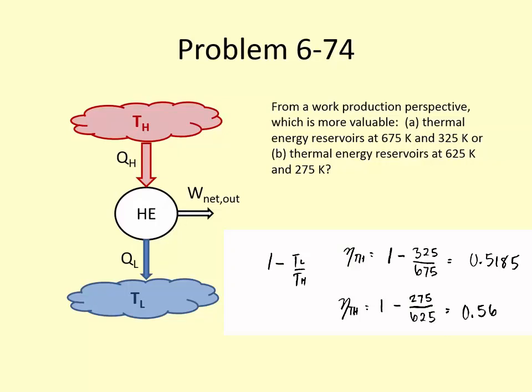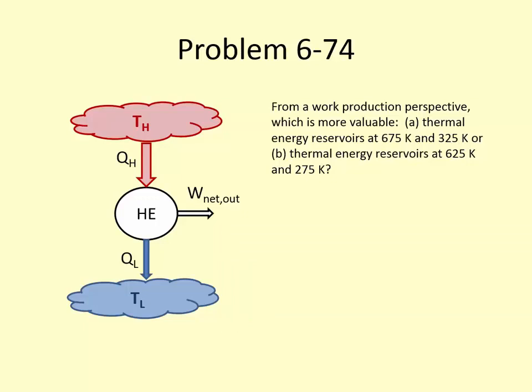So sometimes we have to play a little bit of a juggling act, where we say, okay, in this particular scenario, I'm able to get the temperature up to 675, so that's really good, but how much energy are we expending in the furnace to try to increase the temperature to 675 versus 625? So if we can somehow find a lower temperature reservoir to reject our heat to, sometimes that's just as good as increasing the temperature of the high temperature reservoir. So it's really the difference between those two reservoirs and how we can calculate the Carnot efficiency that will oftentimes give us the best case scenario, or how we can maximize the efficiency of our design or our system. So it's important to look at.